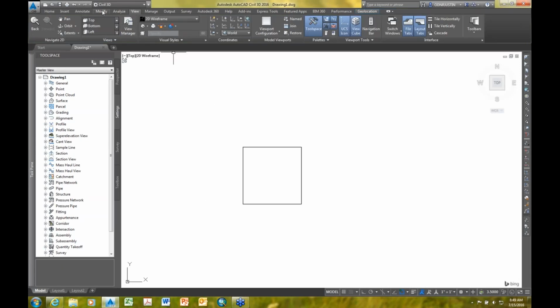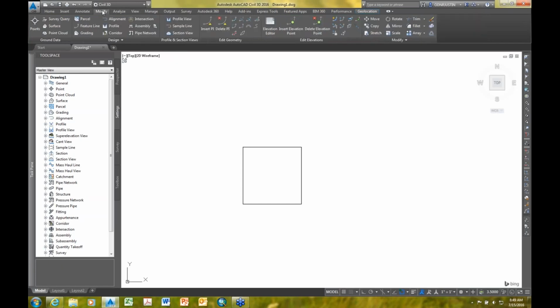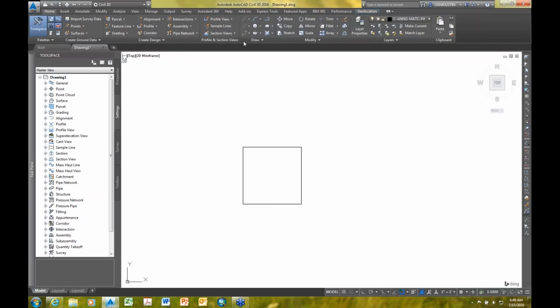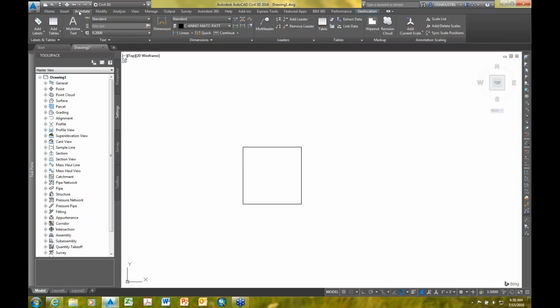Now let's go back here to our drawing that we did for the rectangle. If I go to the Home tab again, we had the drawing tools I mentioned. We also have modify tools, and the modify tools are going to allow you to do a lot of the editing and customizing to all your different line work. You'll also have the Annotation tab, where we can do our text work and dimensioning work.